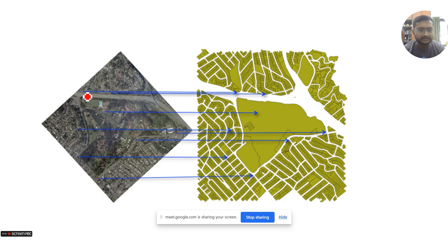So basically, in the image, once we have some kind of corner point of a plot or something on a park which is permanent in nature, we will keep those points as georeferencing points or GCP points. Then we will perform the georeferencing operation and overlay the image which we collected through drone on a particular base.